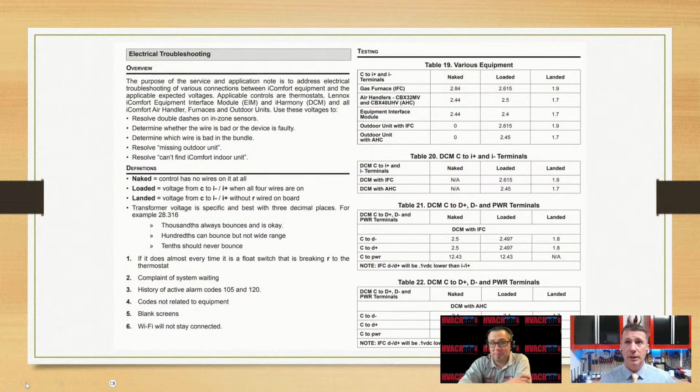If it's not, start unplugging. Check your conductors. Check all the terminals. Check your ground reference. Absolutely.